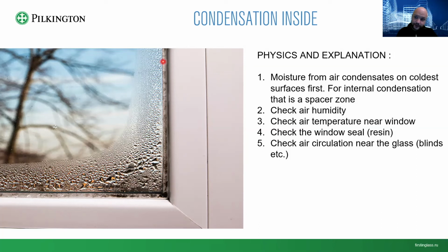And that also means that the better the U value, the bigger the temperature of the inner surface. At the bigger temperature of the inner surface, the less problems you will be having with the inner condensation. On the contrary, the better the U value of your window, the more outer condensation you might be having. But as I've explained to you, that is not a terrible thing.